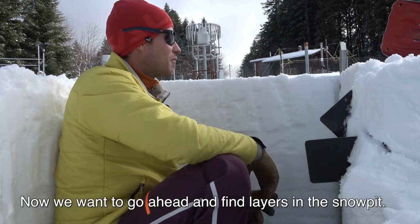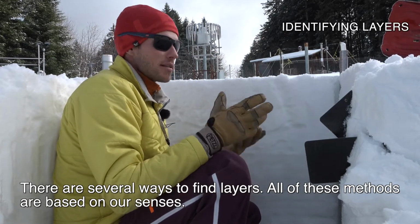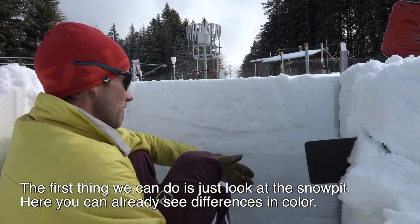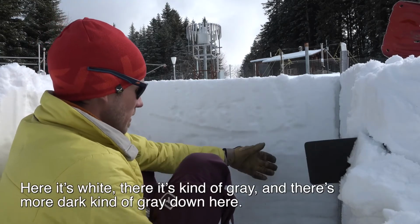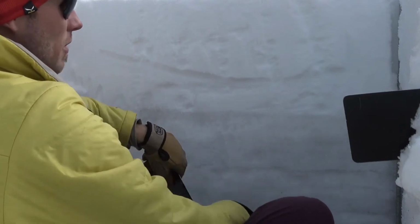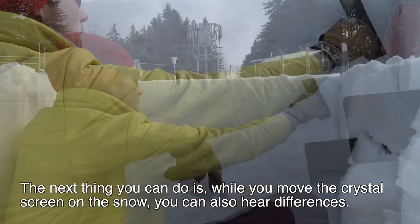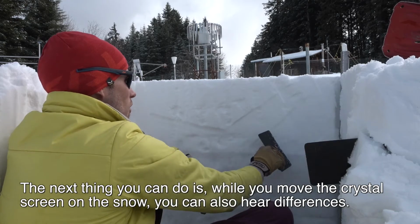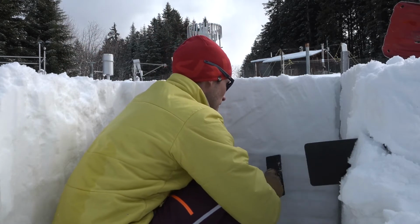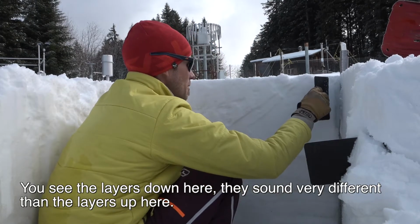So now we want to go ahead and find layers in the snow pit. And there are several ways to find layers, and basically all these methods are based on our senses. So first thing we can do is we can just look at the snow pit, and here you can already see differences in color. I mean, here it's white, there it's kind of gray, and there's something more dark gray down here. The next thing you can do is, while you move the crystal screen on the snow, you will also hear differences. So you see the layers down here, they sound very different than the layers up here.